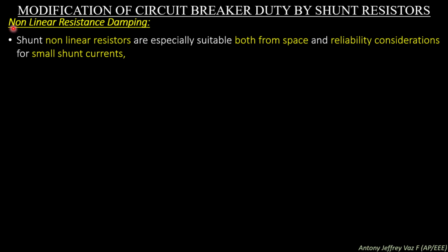Nonlinear resistance damping. Shunt nonlinear resistors are especially suitable, from both space and reliability considerations, for small shunt currents. Where nonlinear resistors are used, the circuit breaker space decreases and the reliability of the circuit breaker increases.